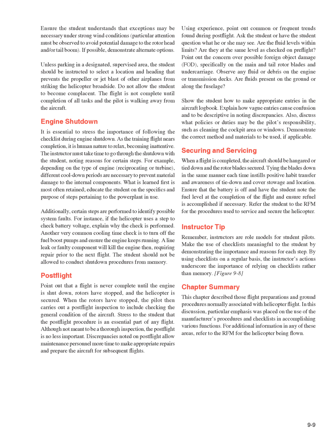Securing and servicing. When a flight is completed, the aircraft should be hangared or tied down and the rotor blades secured. Tying the blades down in the same manner each time instills positive habit transfer and awareness of tie down and cover stowage and location. Ensure that the battery is off and have the student note the fuel level at the completion of the flight and ensure refuel is accomplished if necessary. Refer the student to the RFM for the procedures used to service and secure the helicopter.